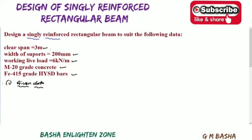So clear span is given as 3 meters, which is L equal to 3 meters, and width of the support, that is B equal to 200 mm, and working live load will be equal to 6 kilonewton per meter, which I denote with LL. Then M20 grade concrete, that is fck equal to 20 newton per mm square, and Fe 415 steel means fy equal to 415 newton per mm square. All these are the given data. Based on this data, we are going to design a beam.